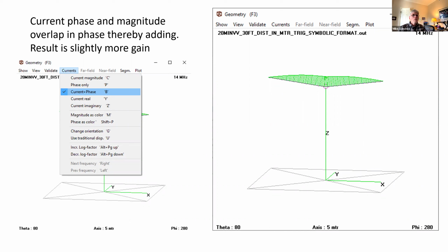So the optimizer for 4NEC2 is like the vast majority of optimizers, and that is it does a local search around the starting point. Now you can get some optimization packages with MATLAB where you can make a wider search range, but the wider you search, the longer it takes, and also the less stable the outcome is. So Arie Voors, when he coded this up, he makes the steps around your optimization not too wide.